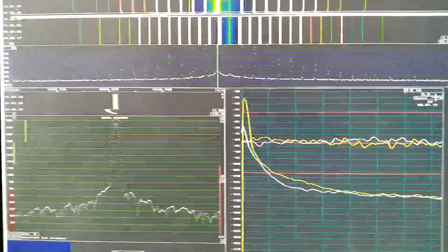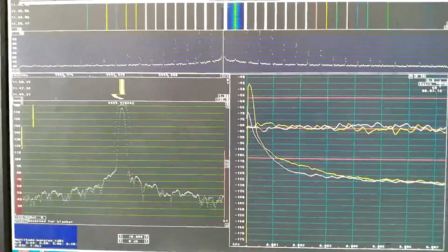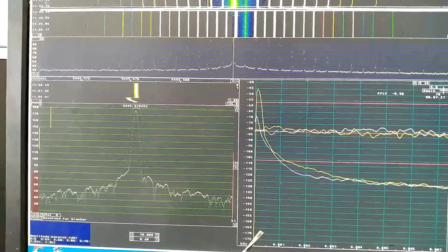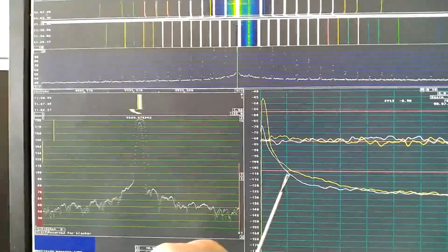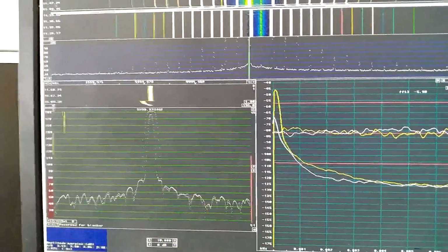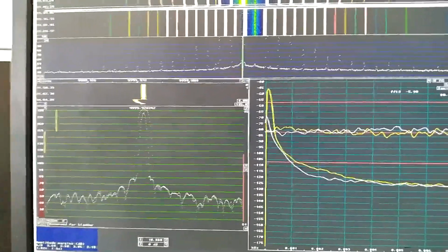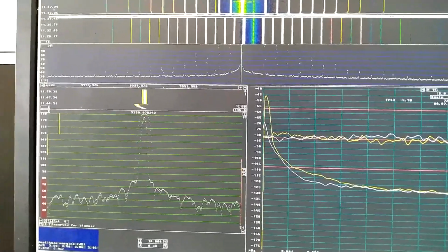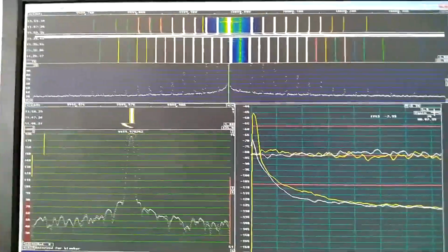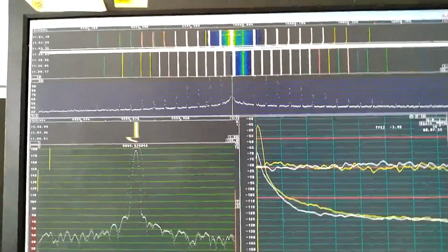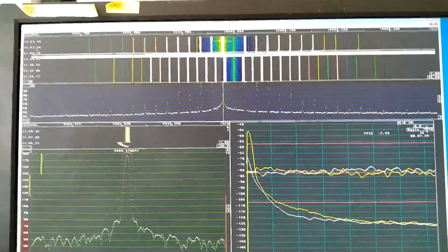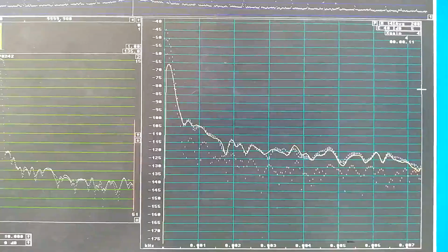Here is what I see at close range. At 1 Hertz, I see minus 104 dBc per Hertz. I have seen a little better than that on the SDR-IP some time ago. I will reset and check, because I started it when it was not really warm.